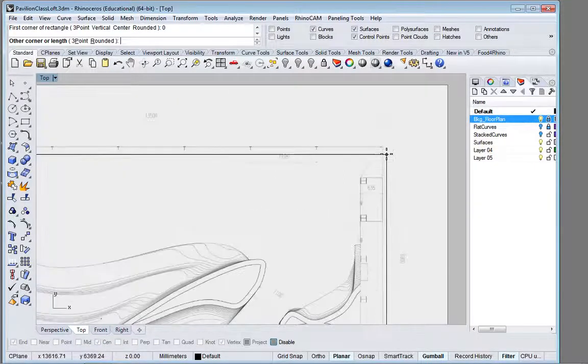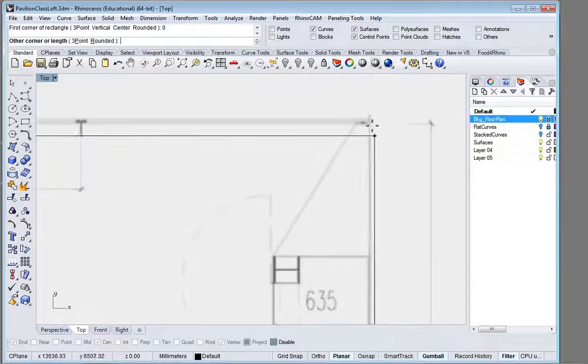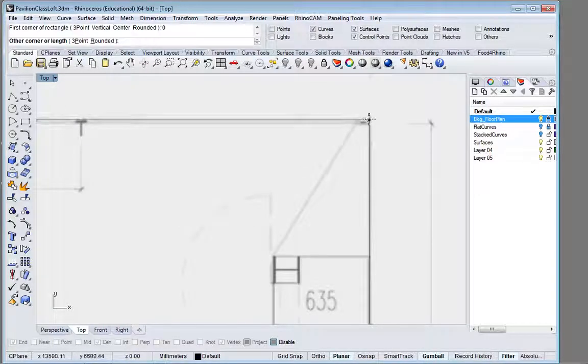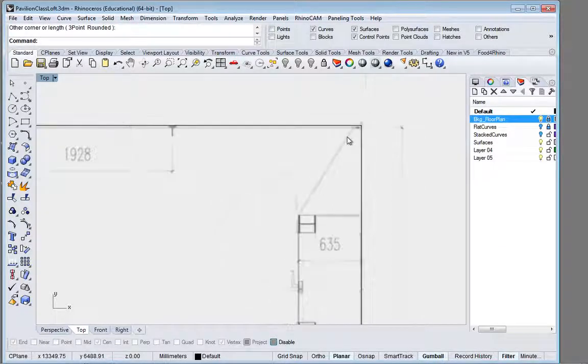And I am just going to come over here. And like I was mentioning to one of your classmates, you want to think about getting in the center lines of these lines that are coming from a raster rather than the outside edges, because those line widths are all based from the center, so the dimensions are going to be more stable if they're based on the center.